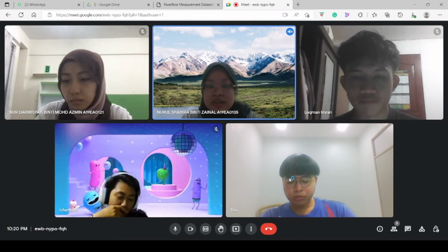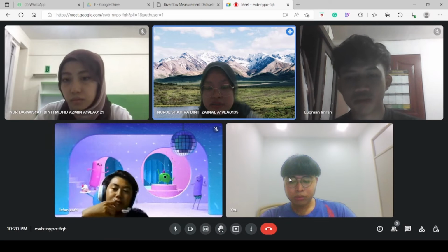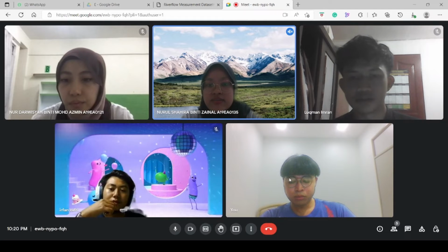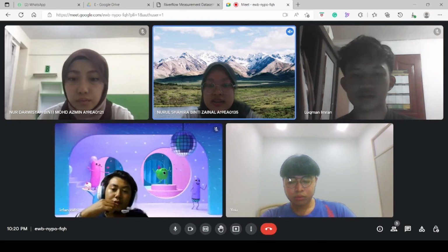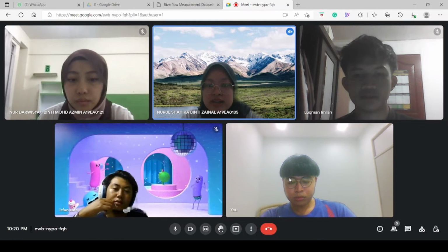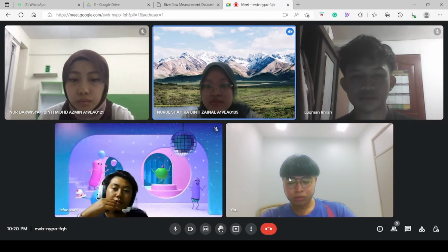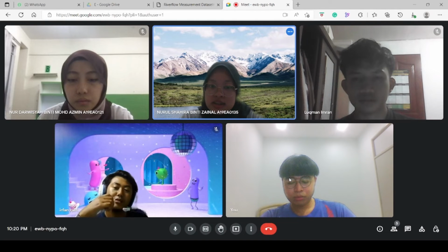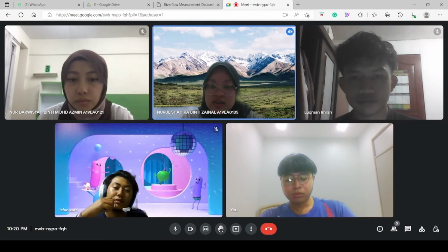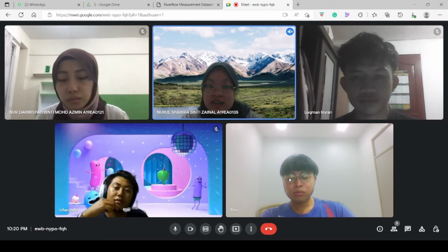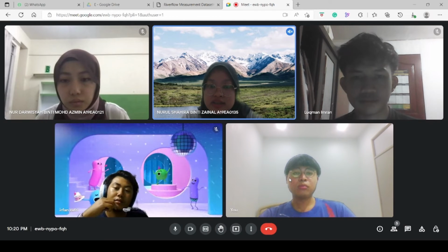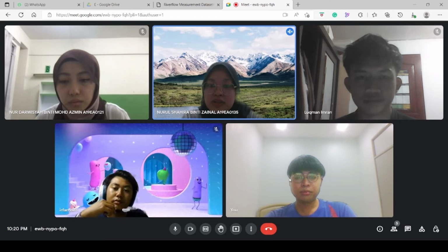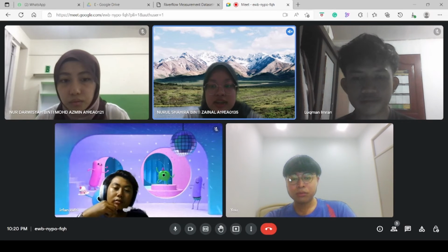Besides, the current meter is not exactly placed at the design depth, which is 0.6 y, which results in inconsistent values of velocity for each section. Other than that, there is parallax error when taking the measurement of depth and width of the river. In order to minimize the error, at least 2 students need to take the measurement to avoid parallax error, and the readings can be done several times to obtain the average. We can also increase the number of cross-sections so that we can minimize the error.